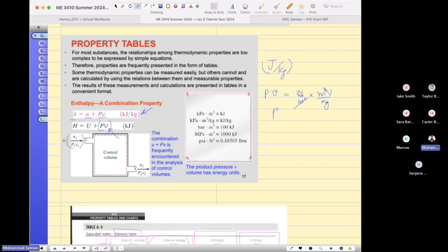Look, when the mass travels, it contains two types of energy: due to the internal molecules plus due to the flow. How much flow is there? When the engineers thought of this, you will study later on that enthalpy is just one combined property. When the fluid is flowing inside a tube, then you should know what enthalpy is. It is a combined property, the internal energy plus the flow energy. This is known as the enthalpy.